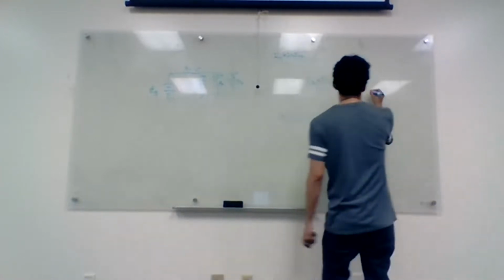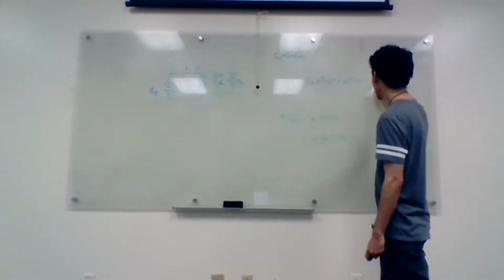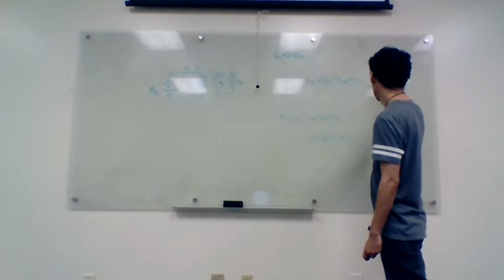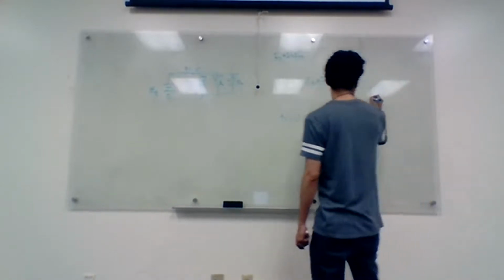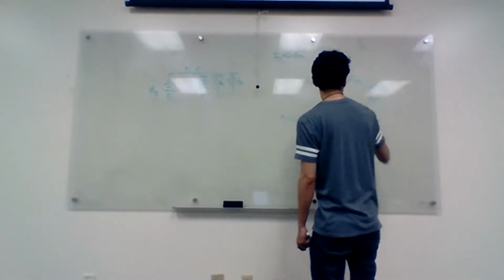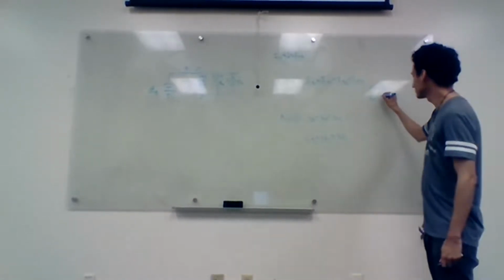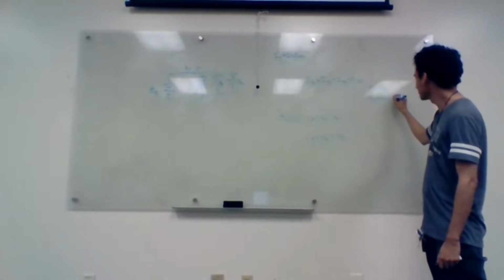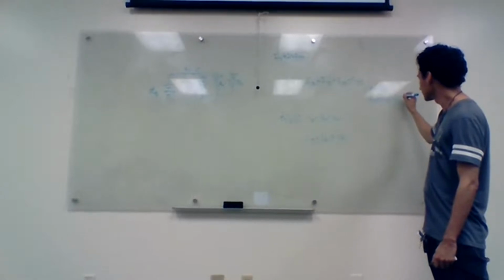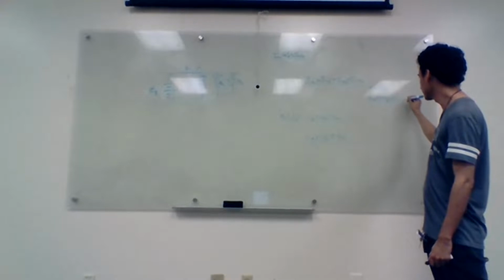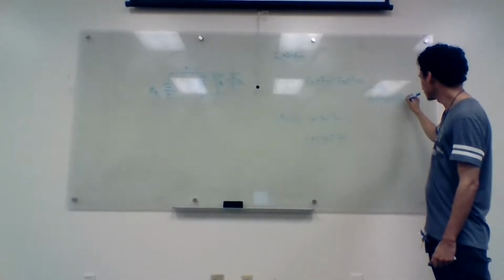So we can say that I_R1 is equal to V_R1 over R1, and say that I_D1 is equal to an exponential bracket, V_D1 over eta times V thermal.